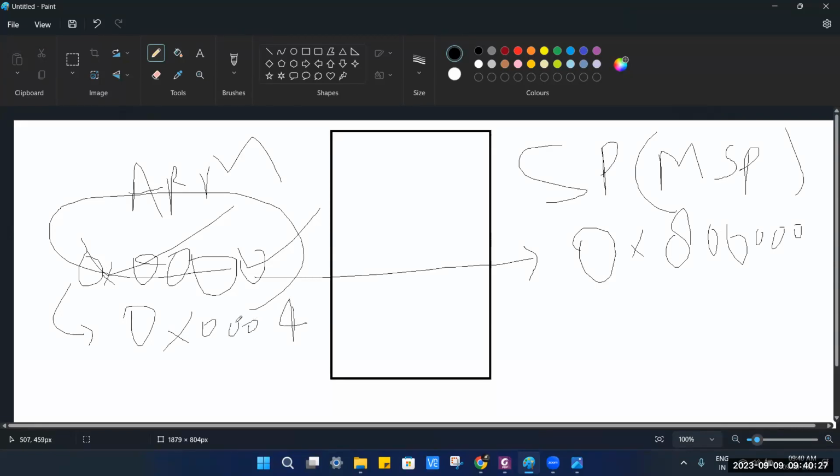That is the next instruction, where the address of the reset handler would get stored. So what would happen in this reset handler? It does some system initialization, maybe because you might have written some startup code for it. Then it will directly jump to the C program you have written, or the main function of your code, and after that the whole program would start executing.